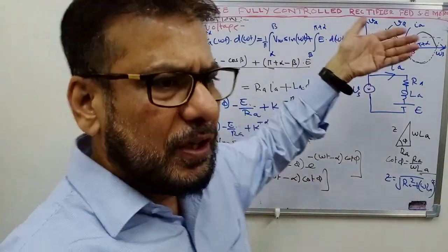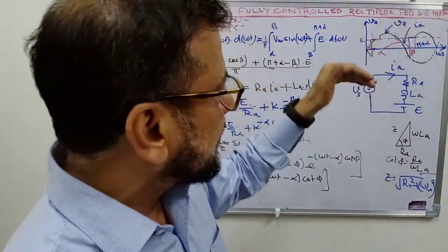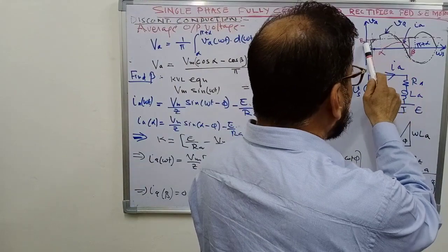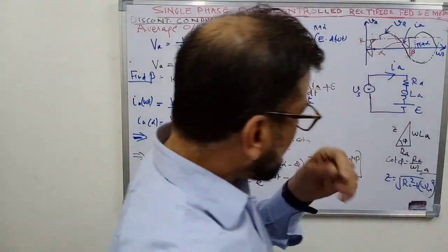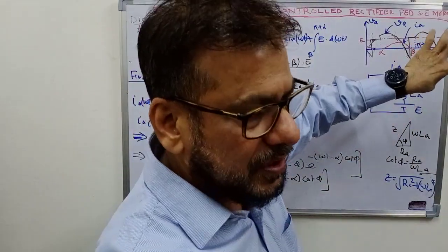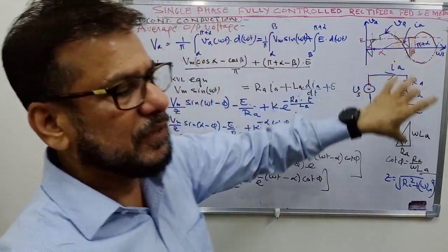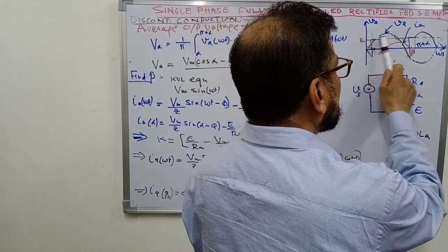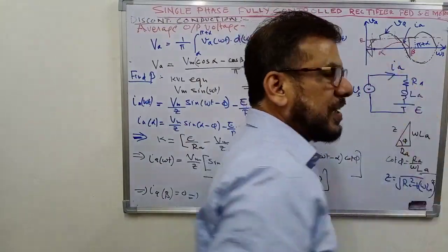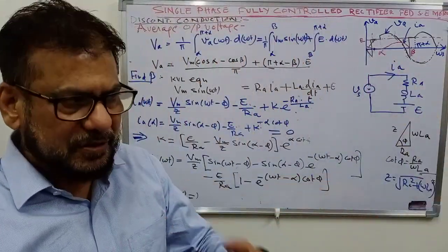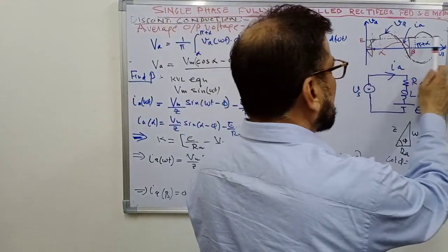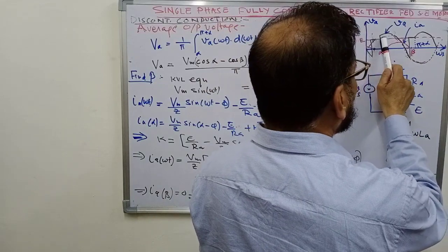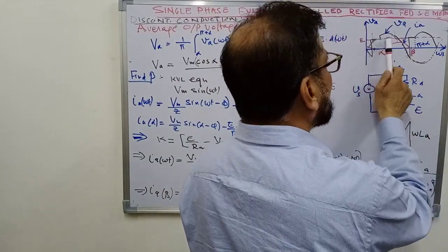So, you recall the previous lectures where we discussed the waveform in detail. We have seen that when the current falls to zero, the back EMF of the motor appears across the terminals of the motor, and the output voltage becomes equal to the back EMF. So this is the back EMF, which is slightly less than the average value of armature voltage. As soon as the current falls to zero, the output voltage VA becomes equal to E, that is